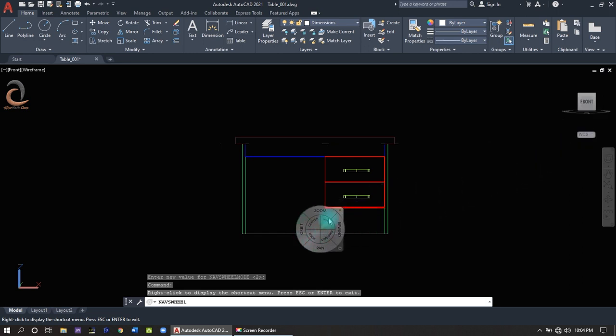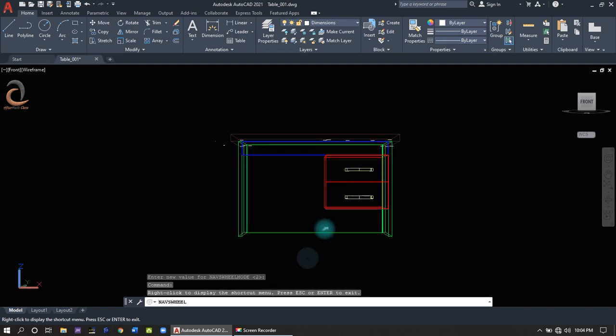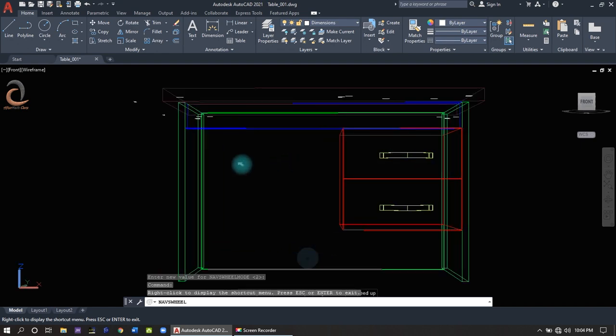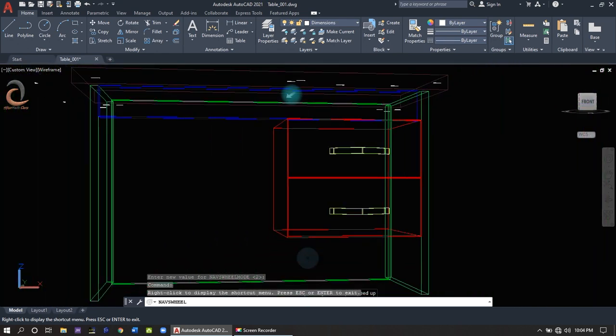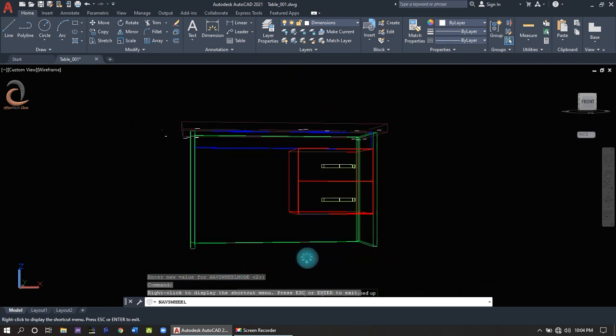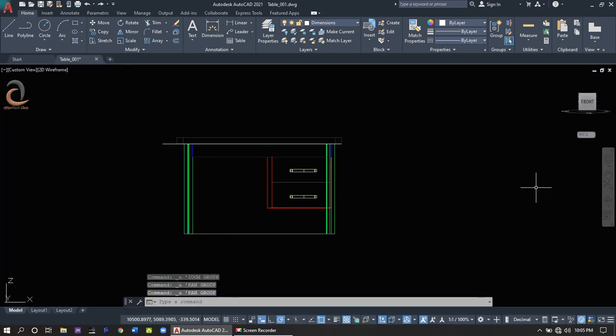Just press on any of the wedges, say Walk wedge, and drag to use the Walk navigation tool. When you are satisfied, release the mouse button to return to the wheel. You can repeat this for any other navigation tool.